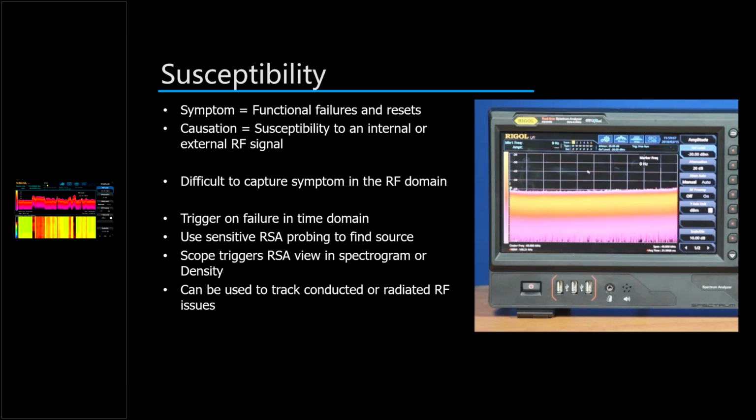So once you've added RF capabilities and some other components to your system, you can see these systems start to interact in unexpected ways. One of them is that the wideband RF envelope of certain devices like mechanical relays can cause you problems on your high-speed embedded systems.